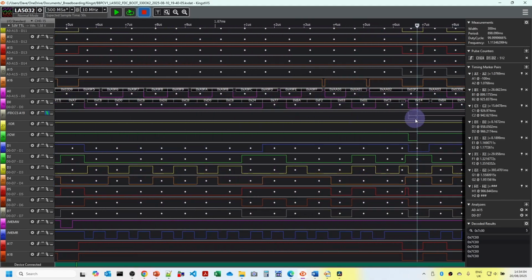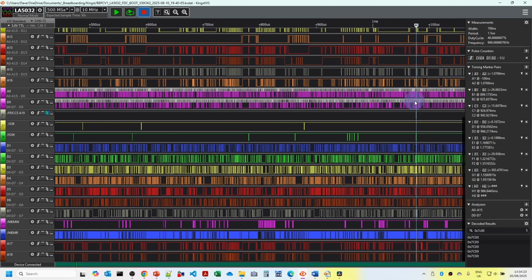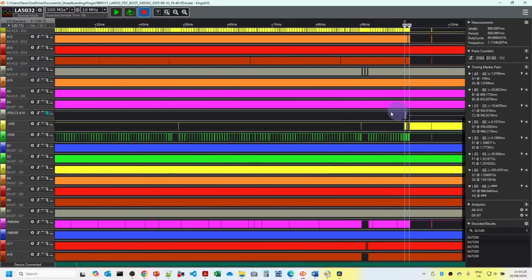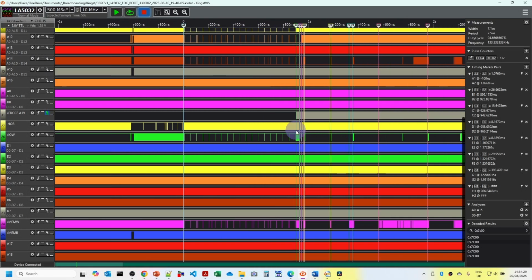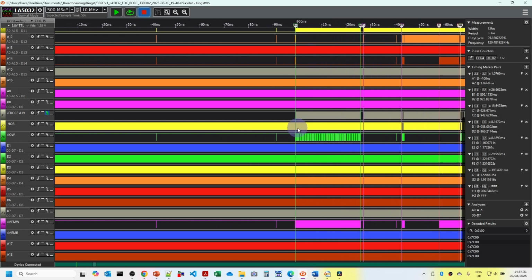And the last bit in this section is that we turn on the drive motor for drive A. That's the lowest bit of the top nibble there, so that'll be bit 4. Setting that on turns on the drive motor. Now you have to wait for at least about a second or so before the drive motor will have spun up. So as we zoom out here, this is the waiting, the polling of the timers to wait until we're up to about a second.